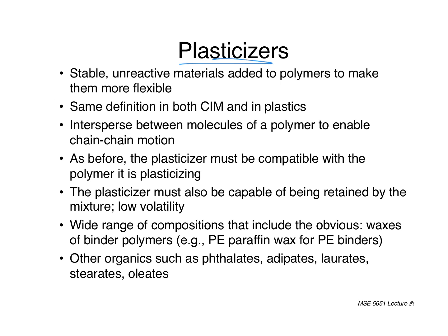And so those of you from polymers will remember plasticizers. And here they do the same thing. They help plasticize this otherwise more brittle polymer phase. And so these are shorter chain polymers that have specific chemical structures that enable the overall binder to become softer. All right, and that is important to us because we don't want a really brittle part that can easily fracture before it even goes into the furnace, for example.